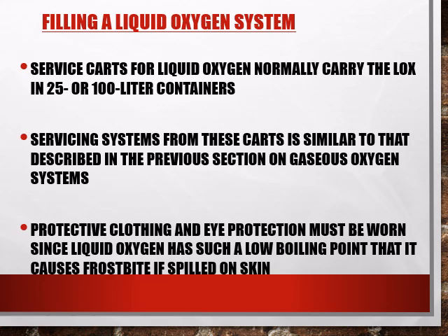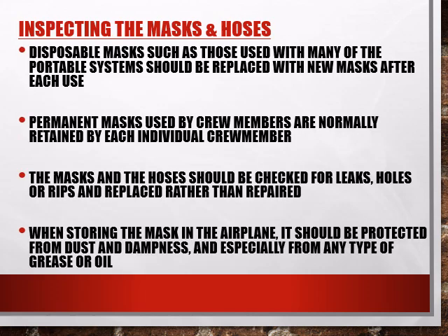Servicing LOX systems involves highly cryogenic liquids, so protective gloves and goggles are a must. The LOX cart connects similarly to gaseous systems, but must be handled cautiously due to frostbite and explosion hazards. Masks and hoses must be checked regularly for damage, cracks, or contamination. Disposable masks are discarded after use. Permanent masks are assigned to individual crew members and stored away from oil, dust, or moisture.